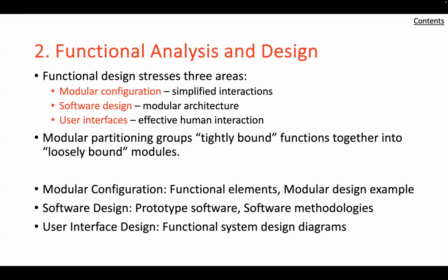2, when assembled with the other components, a component will perform its function properly and without further adjustments. 3, a faulty component can be replaced directly by an equivalent interchange component. 4, a component can be upgraded internally without affecting the design of other components. A system designed with the above characteristics is referred to as modular or sectionalized. These characteristics apply to both hardware and software components. They depend on physical as well as functional interactions, but the latter are fundamental and must be defined before the physical interactions can be established.